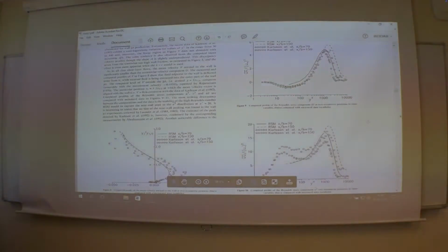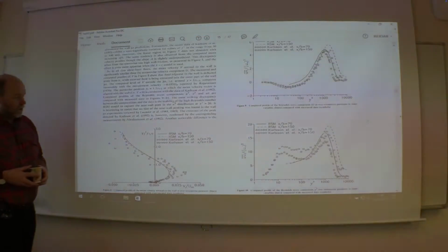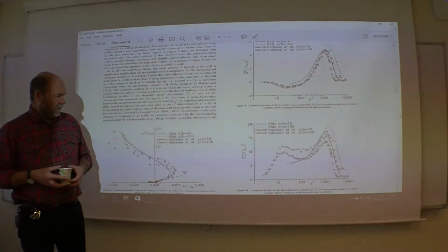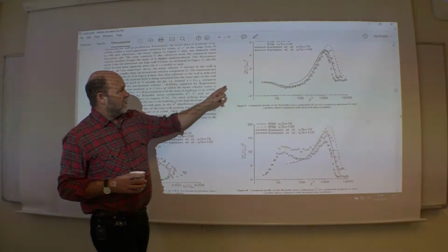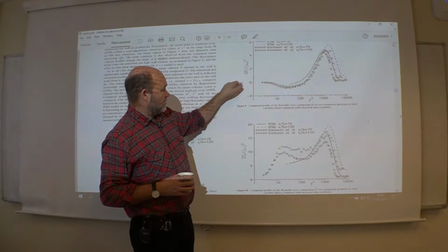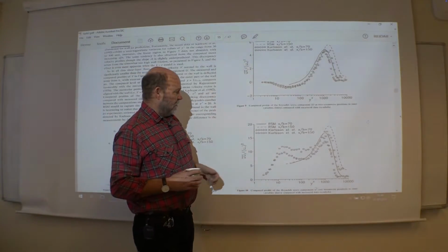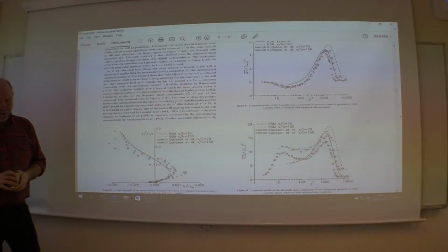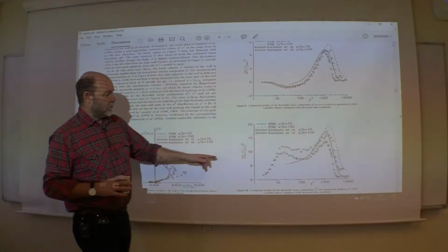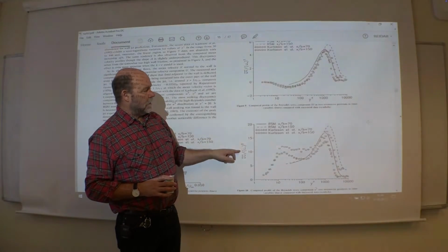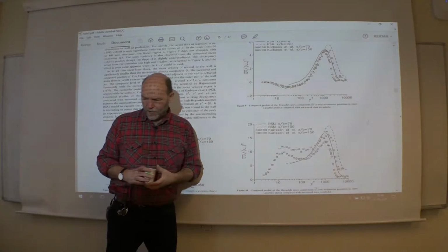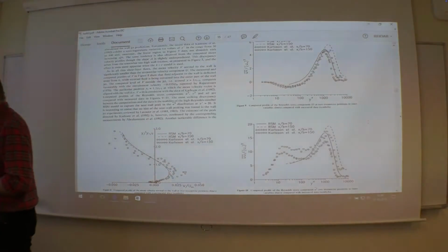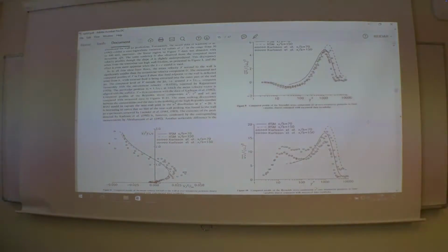So looking into more complex turbulent quantities, the shear stress and the normal stress, then of course you can't actually use K epsilon. They don't have these different components of the Reynolds stresses at all. Then you have to use either ASM or, as here, a full Reynolds stress model to find them.